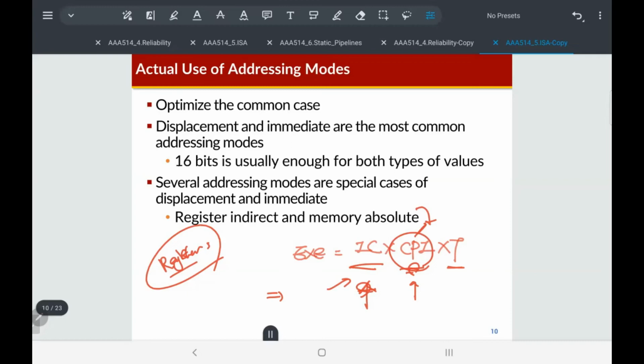The registers are very precious resources. If the registers are occupied by many instructions, then we need to replace the data from these registers, and if the data should be maintained, we need to store it to the main memory because of the pressure on the register file. That is another disadvantage of the RISC type ISA.